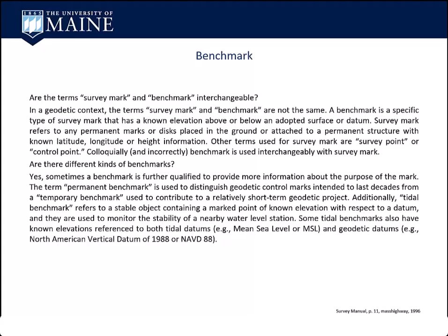And sometimes you have to be on those tidal benchmarks because somebody wants a ship to go under a bridge at high tide. So you need to be able to say, this is your clearance at high tide. If you built a bridge and people can't travel under it except at certain times, once or twice a day, depending upon if you have 2 cycle tides or not, it can be a problem. Or you just hit the bridge.